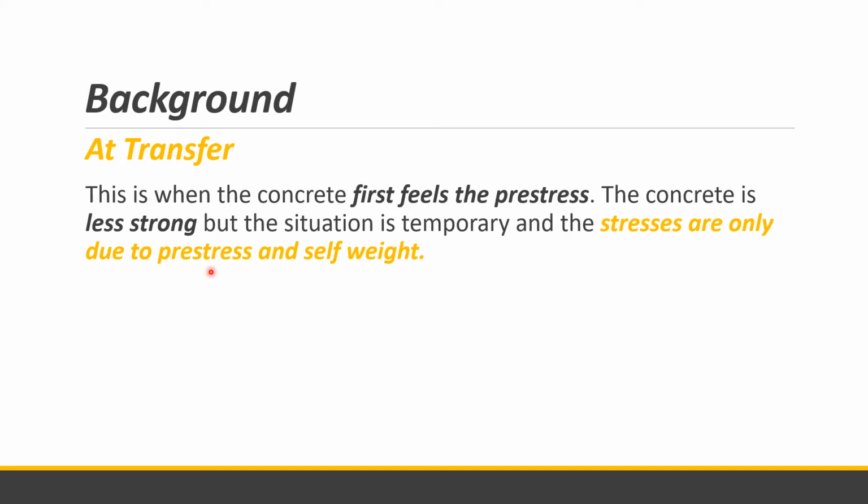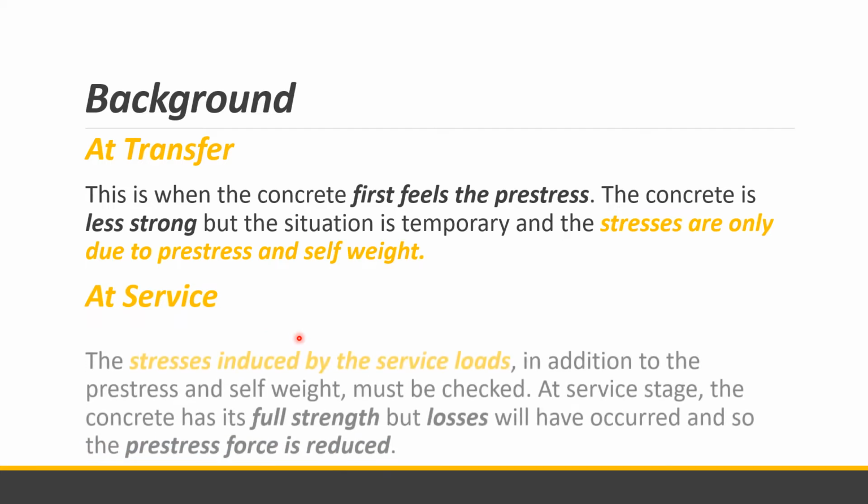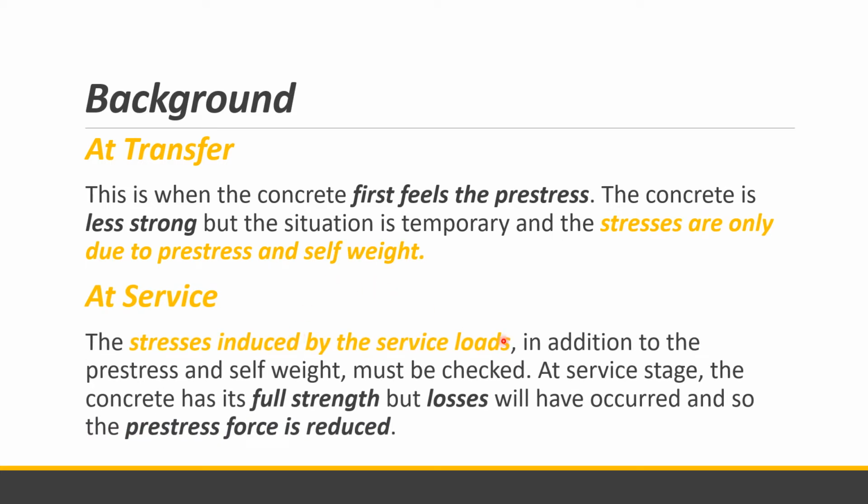So yung pag-apply ng pre-stress na load or force, and then yung self-weight nung concrete. Hindi pa kasali yung service loads, yung applied loads. Hindi pa siya na-install sa building or sa paggagamitan ng mga members. Now, at service or at loading, pag na-apply na yung load, the stresses induced by the service loads, in addition to the pre-stress and self-weight, must be checked. At service stage, the concrete has its full strength, but losses will have occurred, and so the pre-stress force is reduced.